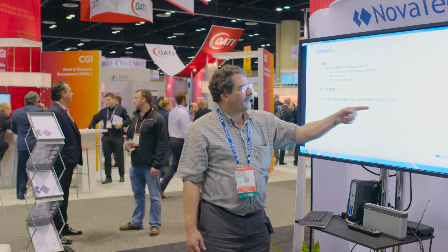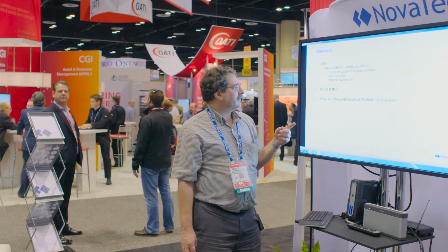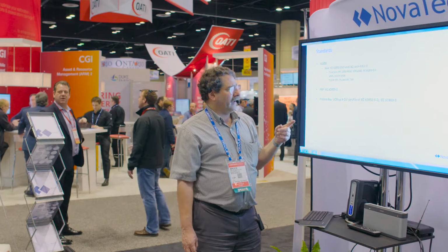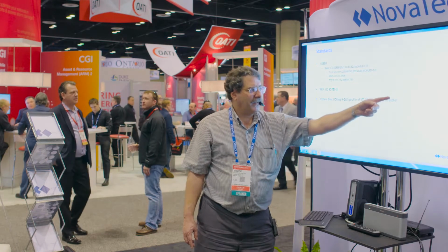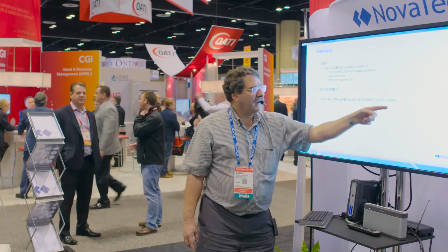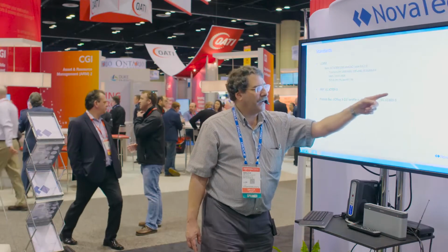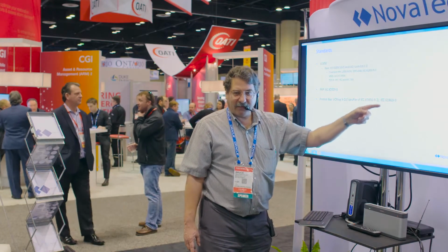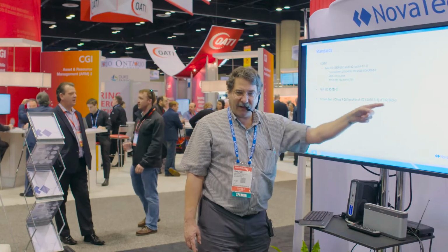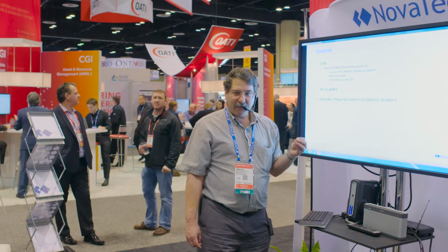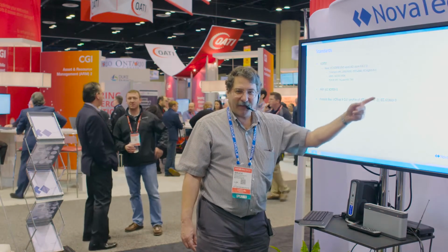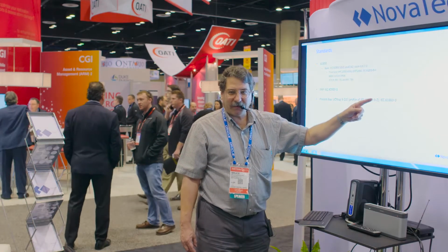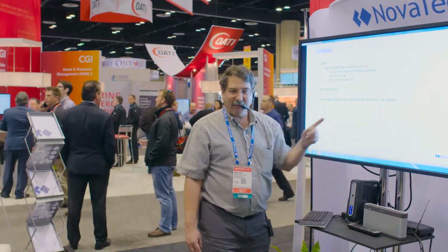There's also a new standard for process bus coming out, 61869-9, which came out of the instrument transformer group. So they're probably going to take over the verification of this. One of the things they added on the merging unit is transient information. If you're familiar with synchrophasors, they have the same kind of issue when a transient occurs. All the filtering algorithms can get out of whack. This one specifies essentially all the filtering algorithms, so all the devices will give you the same information.